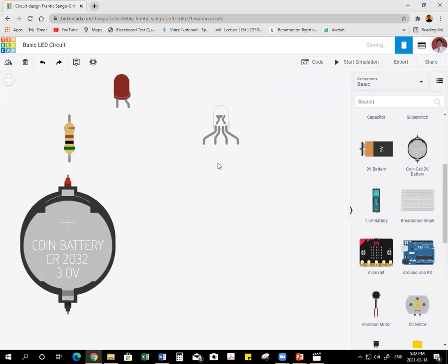Now for this RGB connection, connecting all to positive at a time is not good, because I have to show different colors of light at different times. I want to turn on only red light, only green light, only blue light. How to do that? For that we need 3 switches, so that at a time only one color of the LED can glow.